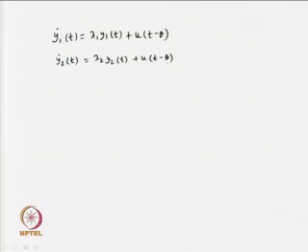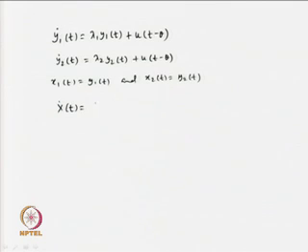Now, if I introduce the state variables x 1 t and x 2 t, let x 1 t is equal to y 1 t and x 2 t is equal to y 2 t, then that will enable me to write that in the state equation form, giving us x dot t is equal to [lambda 1 0; 0 lambda 2] x t plus b u t minus theta.